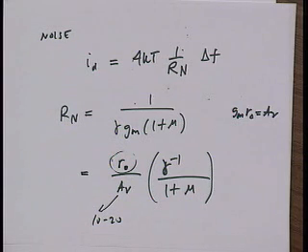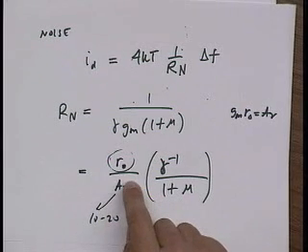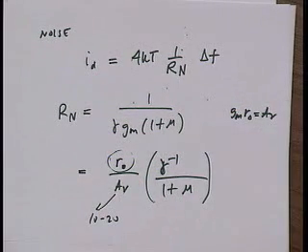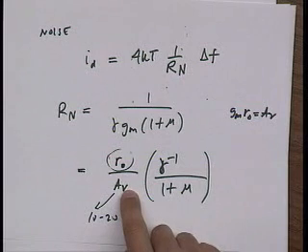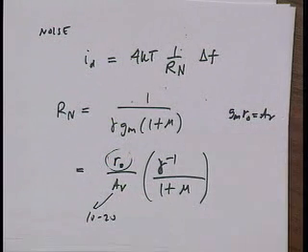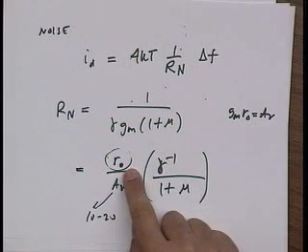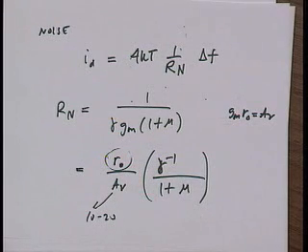Yes, it's bad, right? It's terrible, because this current source is good because it gives us high output impedance, but it's bad because it's giving us a lot of noise. The smaller that resistance, the more current noise we get. So, unfortunately, using a current mirror means that it's very noisy, and it's going to add a substantial amount of noise. If you could use a physical resistor with resistance RO, you'd be much better off, because it would contribute very little noise, 10 or 20 times less noise.